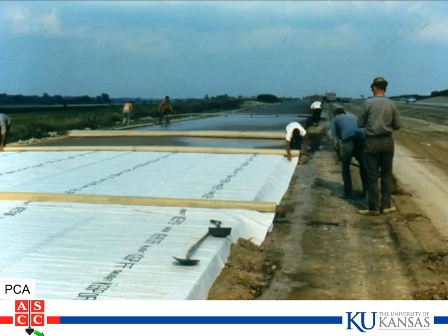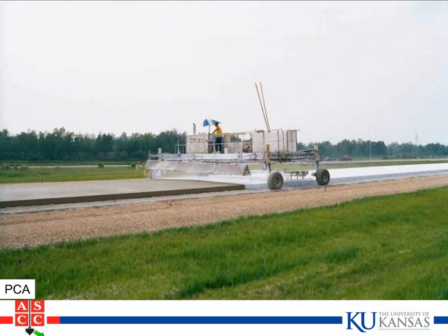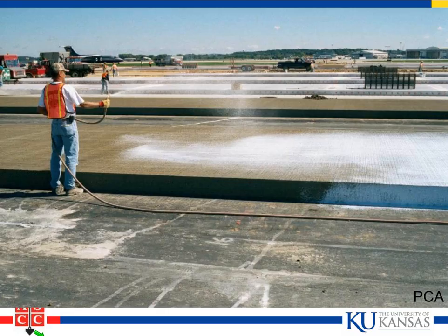Here's an old slide from PCA using waterproof paper on a paving job. More likely, you're going to see a curing compound being sprayed down by equipment, getting a nice good coverage. A lot of times we see this. This is not unusual at all. Take a careful look, and you see that although he's getting part of it covered well, he's not getting the whole thing covered. Now, one thing to keep in mind about curing compound or surface sealers like this is they do not stop evaporation; they slow it. So it's better than nothing, but it's not going to be as good as if you can actually keep water on the surface of the concrete throughout the full time of curing.